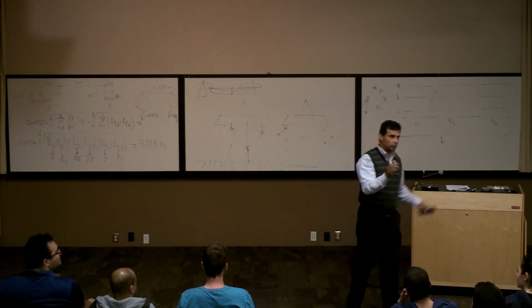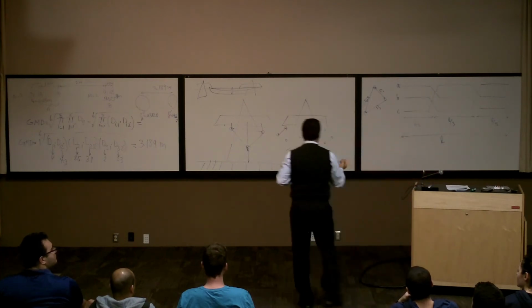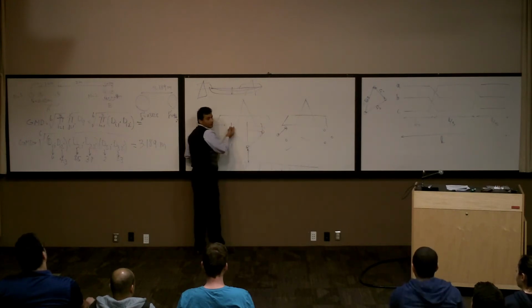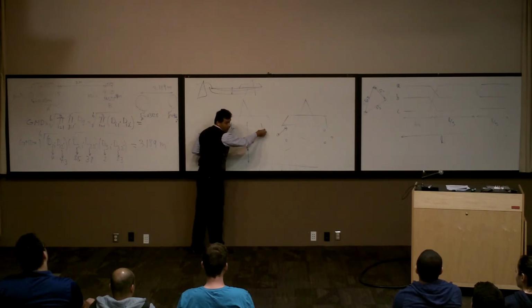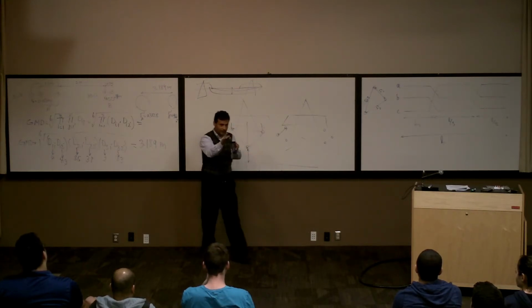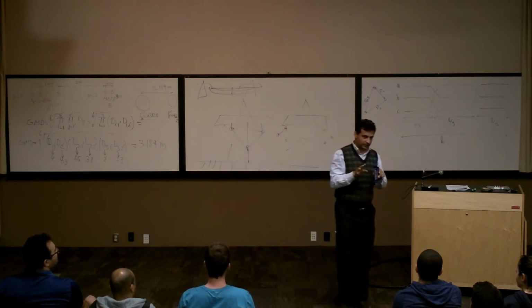That's the reason they don't do it at every tower, because you have to pay the cost to bring the wire, for example, from here to the middle. As we mentioned, these are high voltage, so without isolation we cannot bring it here. It's going to be next to this one, and the other one is going to go this way, or else they're going to pass each other, right? You have to put isolation around it to not cause a short circuit. It costs money.